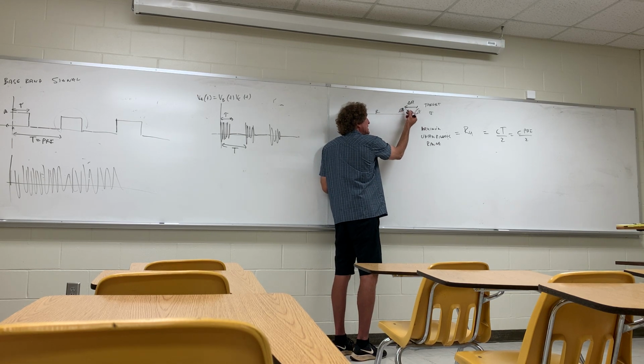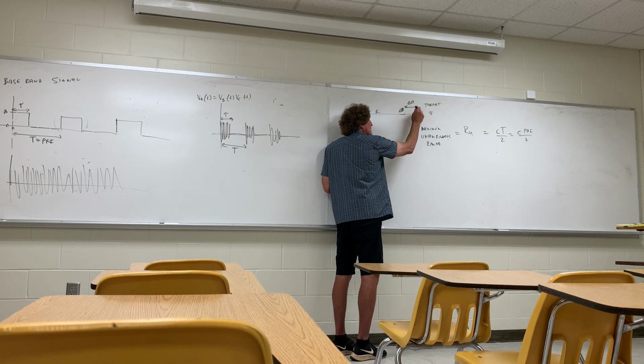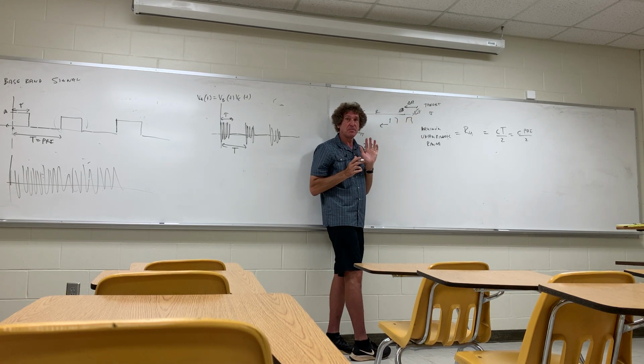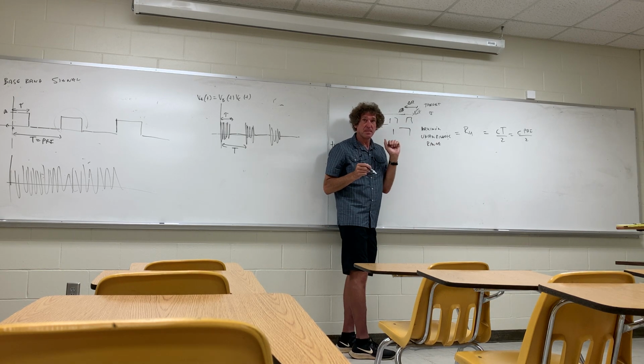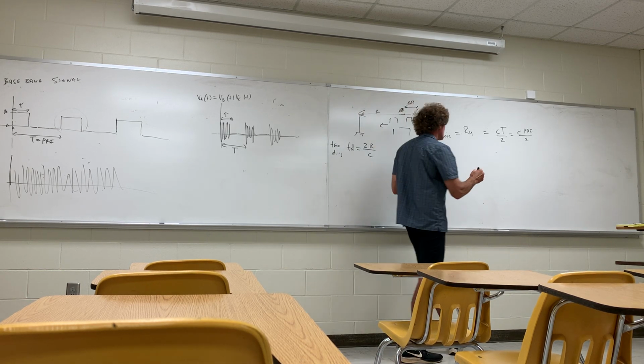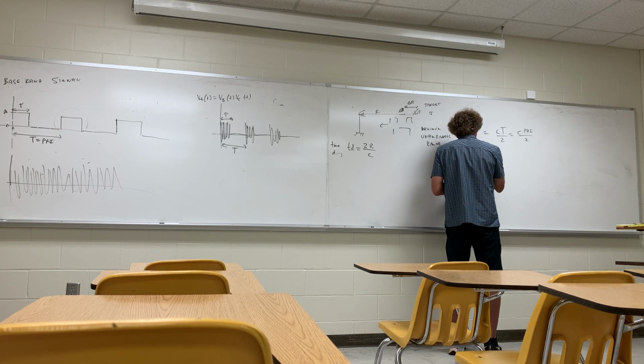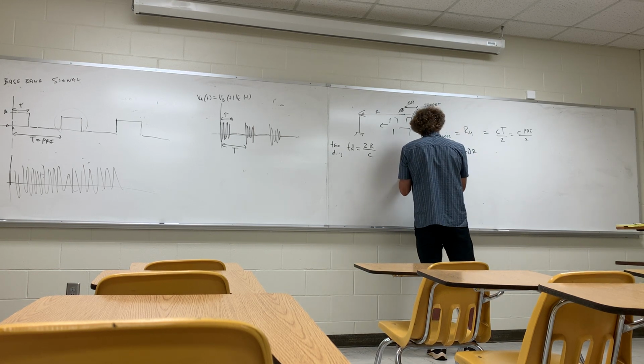Then it hits. The leading edge hits and it starts scattering back. Still, this waveform is going forward. It hits here. Then when it hits this thing, it starts scattering back. Technically, we should have two pulses like this coming back at us. Do y'all follow me? Just think about that. But if all of a sudden these things get too close, we only get one pulse. It's overlap. And that delta R, now this is called the range resolution.